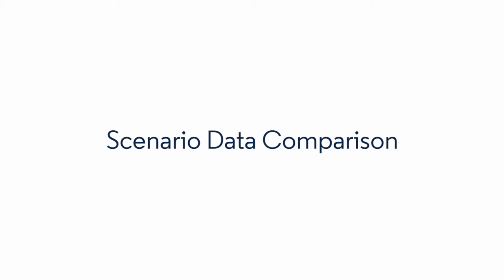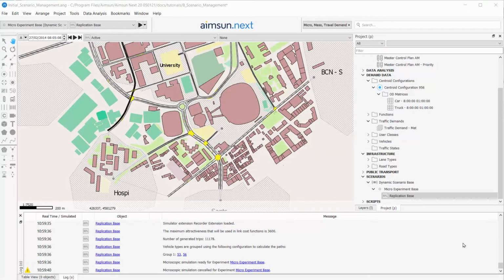We are going to look at how you can compare different scenarios and how you can create different scenarios with different parameter sets using attribute overrides and geometry configurations. The purpose of this exercise is to compare the results of two different scenarios. We're going to create some different scenarios with different traffic demands and signal timings, and then compare them.